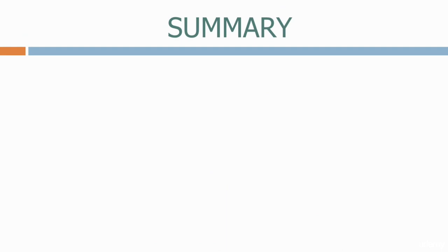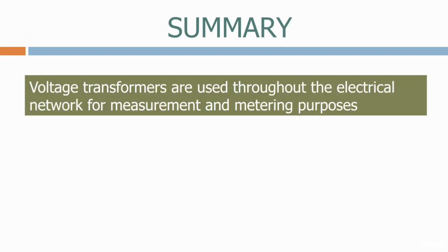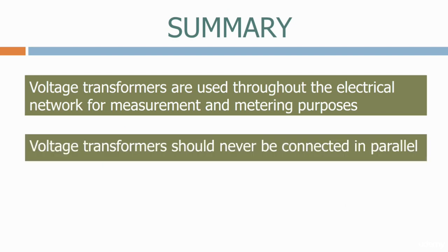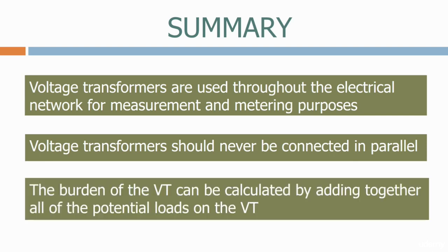Let's summarise what we've learned today. Voltage transformers are used throughout the electrical network for measurement and metering purposes. Voltage transformers should never be connected in parallel. The burden of the VT can be calculated by adding together all of the potential loads on the VT.